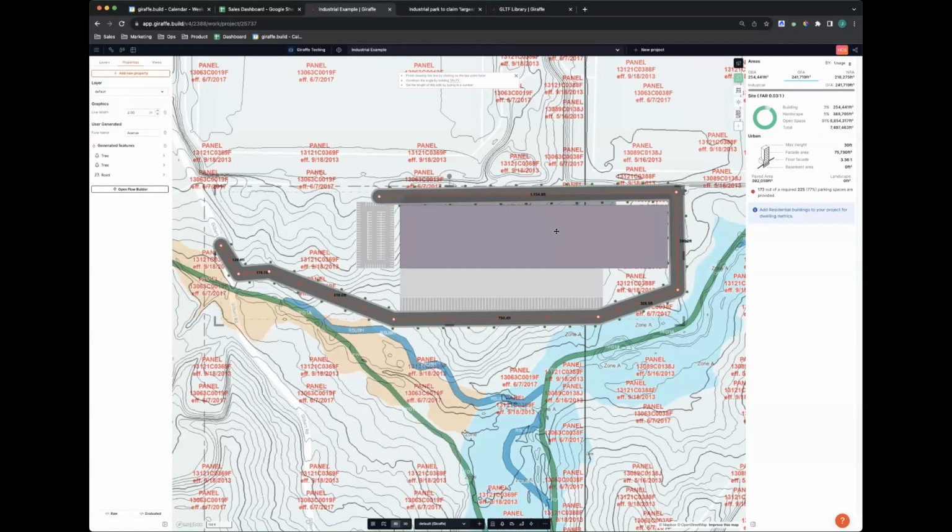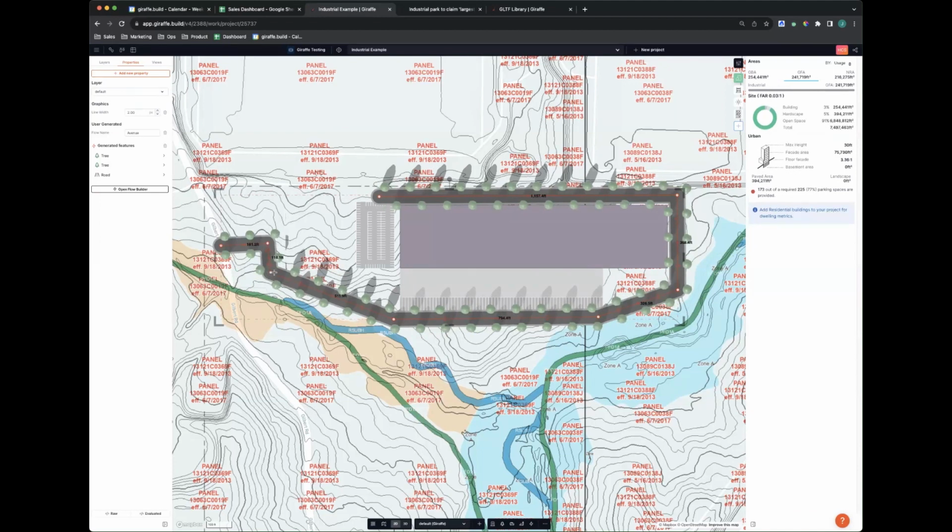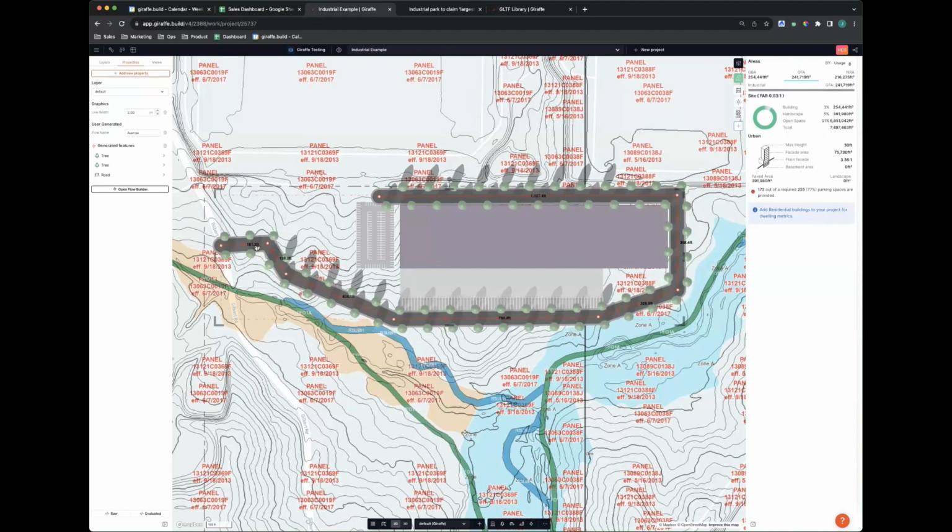Okay. Now you notice when I do that, a couple of things are going to stand out to you if you do industrial development. One is this road is extraordinarily wide. It's way too wide. Two is the corners are way too sharp. You can't get a truck around this corner. The trees are nice. Maybe overkill, depending on what your investment mandate is, but how green it really is. So let's go and mess with it.